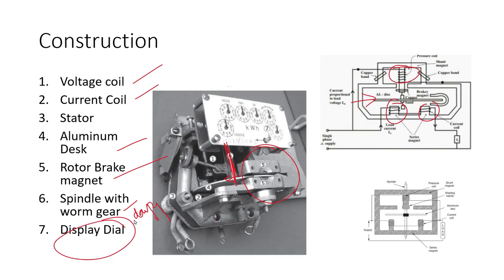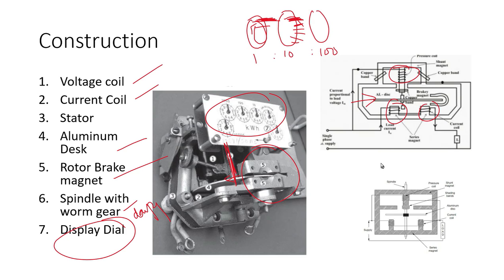Okay, and the display. Display dials are mechanical dials, and these are connected to a watch like mechanism in which, let's say, one dial is like this and it has a wire, a metal gear, and here is another and it has another metal gear. So when this thing rotates one time, it will make this something go a bit forward, and then second time a bit more forward, more, and its ratio is 1:10:100 or something. So this is the mechanical structure of these things.